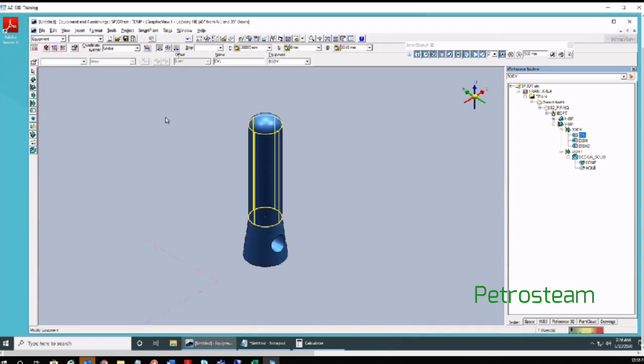You will quickly select this shape, the top shape or the bottom shape. If you try to select the bottom, once the question mark appears, you can see cylinder, dish 2, or a cone shape, which is in the bottom skirt. This is about the locate drop down, and how you can use it as per your requirement.